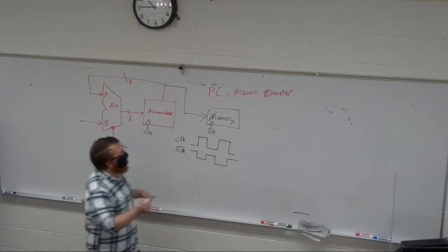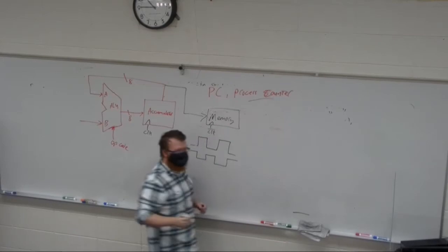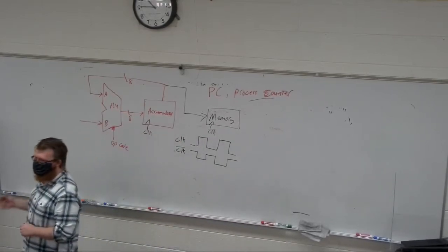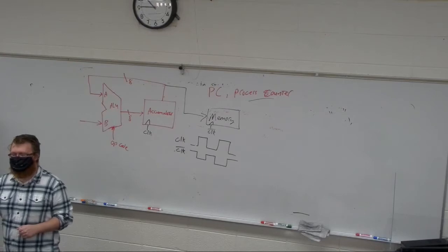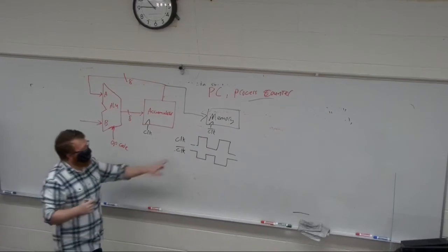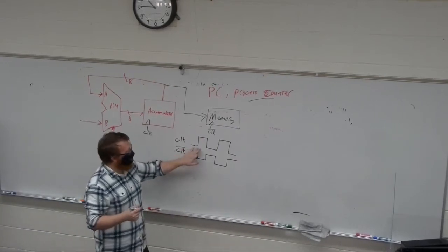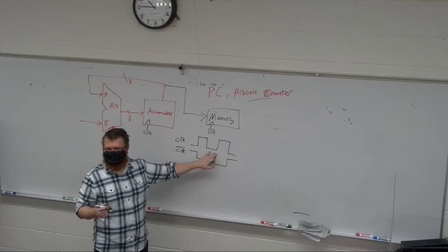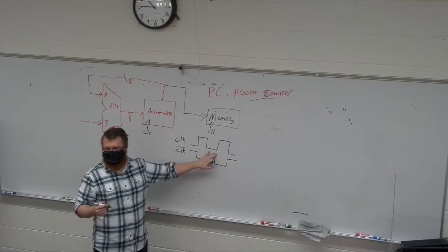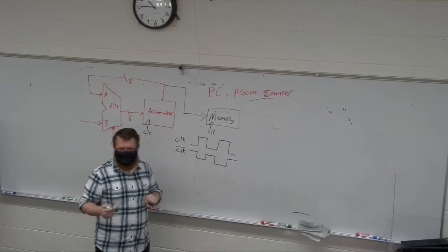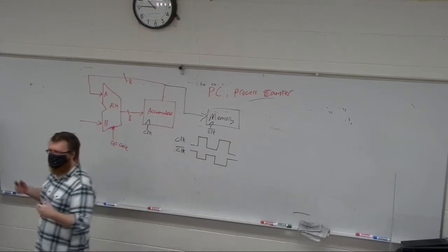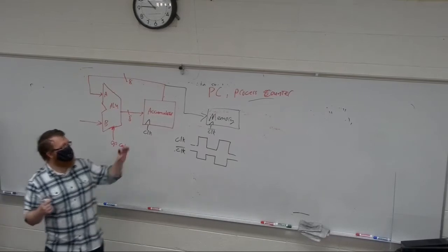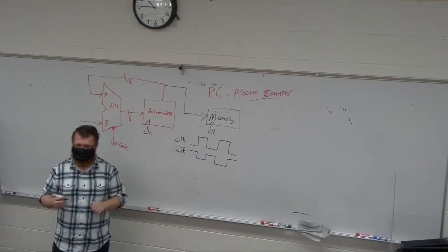Because there will be times that we don't necessarily want to update the process counter on each clock. So if we have this clock ticking along, each rising edge, we're going to update the process counter. We may have a situation where we don't want to update the process counter each clock. So make sure to have a clock enable on your process counter.